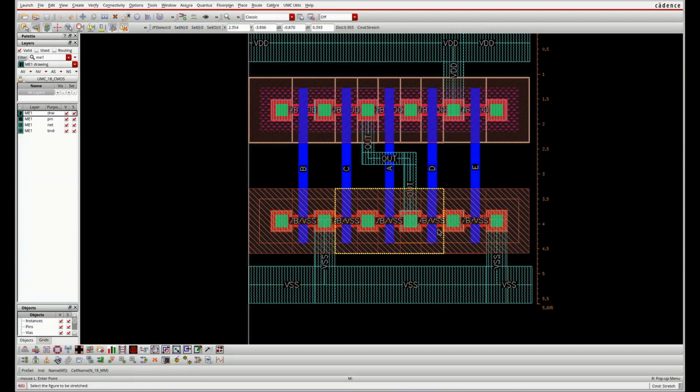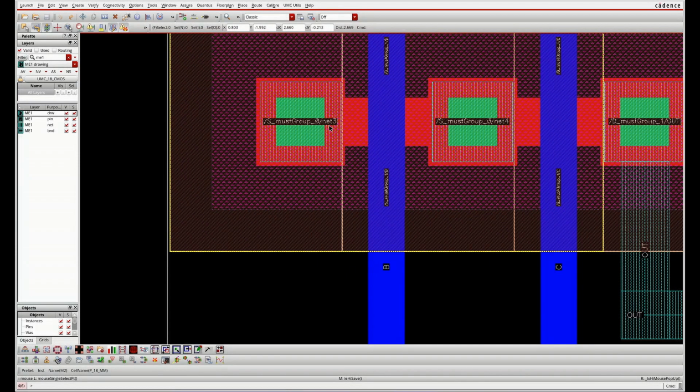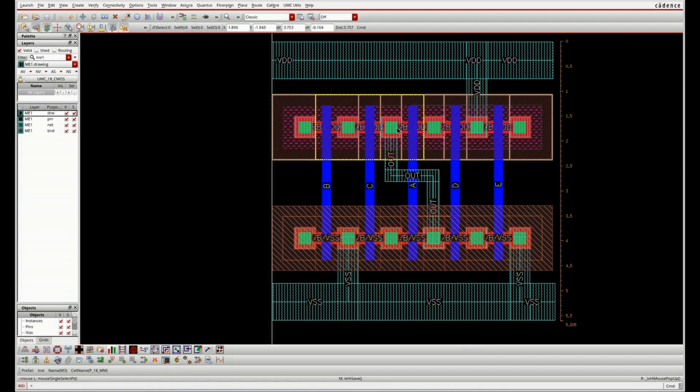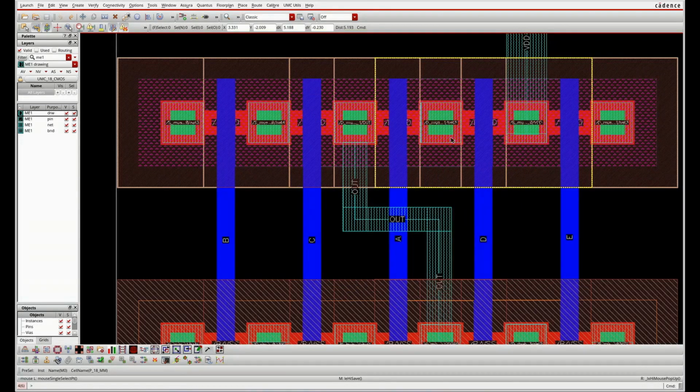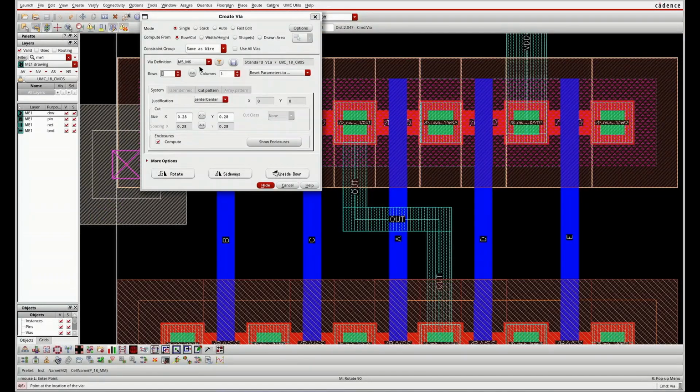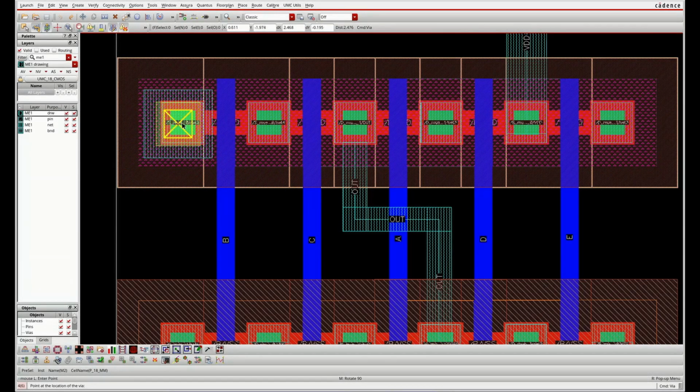So finally the alignment is over. Now you can do the rest of the wirings. Suppose this is net 3, so you have to connect with net 3 here. So use a different metal. For using a different metal, press wire, M1 M2 wire, keep it here.